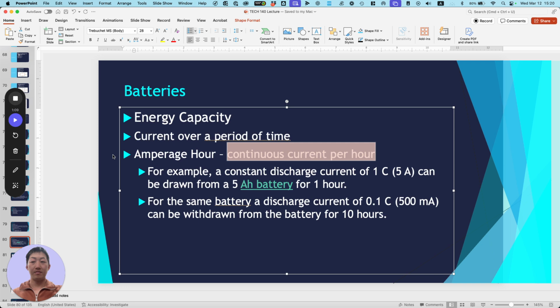Okay. Does that make sense, the leads? You can see what it's doing when you're balance charging: it's checking and making sure if one cell needs a little bit more voltage, it'll just give it to that one particular cell. And this is what I note right here. I say each battery cell needs to be within 0.05 volts of each other.